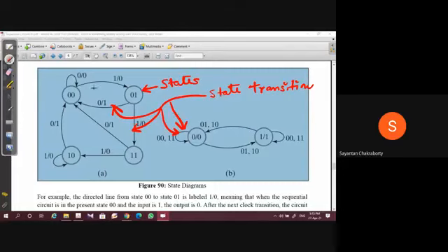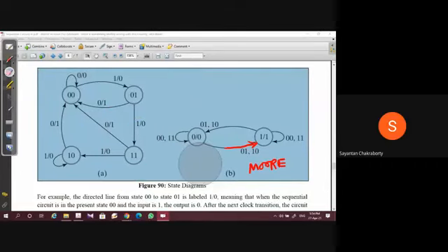If a line starts from a particular state and returns back to the same state, it means that if these conditions are satisfied, then the state doesn't change. And this again means if these conditions are satisfied, then the state moves from this state to this state. Obviously, these two correspond respectively to a Mealy and a Moore model. Let us first start with the Mealy model, which is the state diagram corresponding to the first circuit that we have drawn.